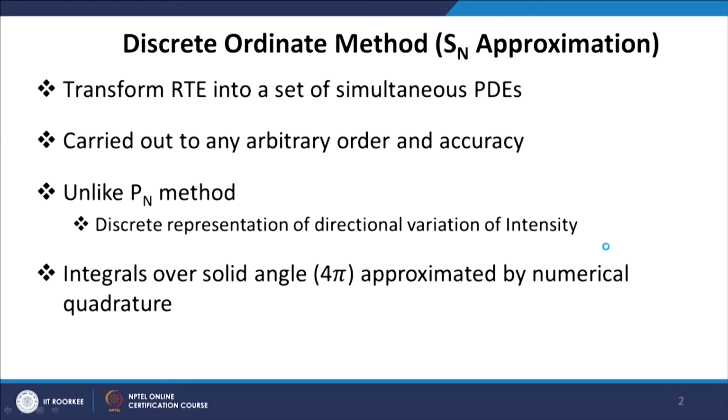So, the objective is the same: we have to transform our RTE, the integral differential equation, into a set of partial differential equations. We can choose as many discrete directions as we want. Of course, the directions have to be decided judiciously, and we have to integrate over the solid angle of 4 pi.